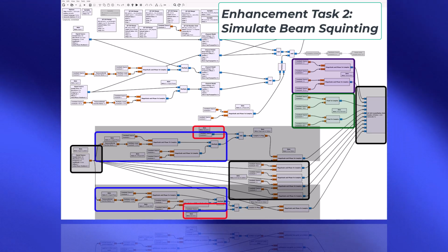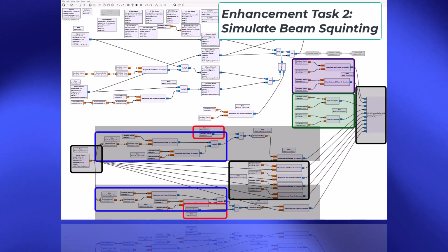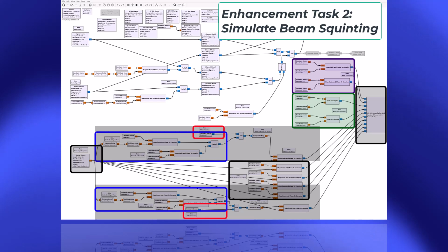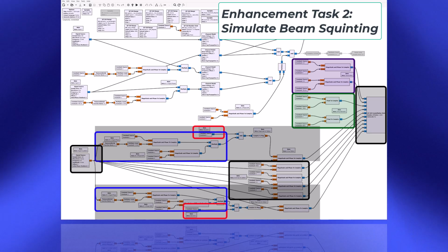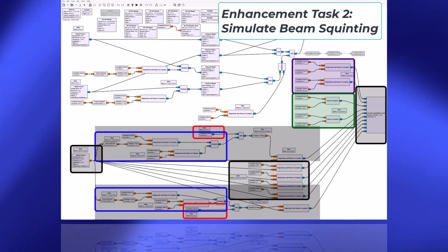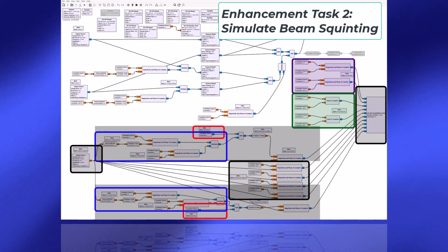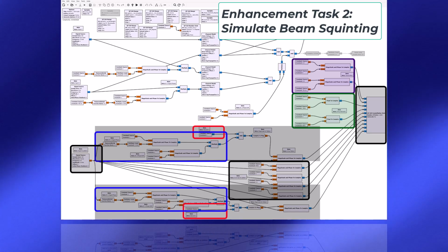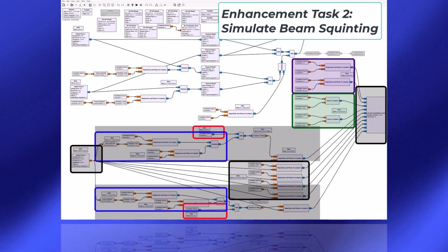And the element spacing is specified using a slider in wavelengths, but those are wavelengths at the reference frequency. The ideal array pattern is calculated assuming that the signals are at the reference frequency, and it uses a wavelength that corresponds to the reference frequency. You'll also want to plot a non-ideal array pattern, and that will be the pattern of the array at some frequency other than the reference frequency that you select using that slider.